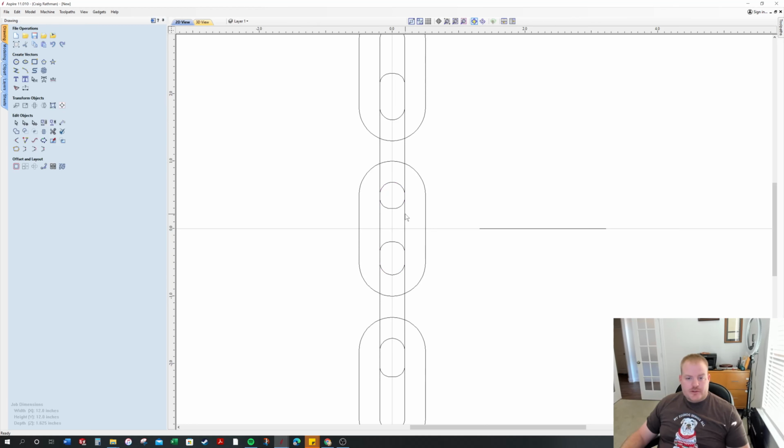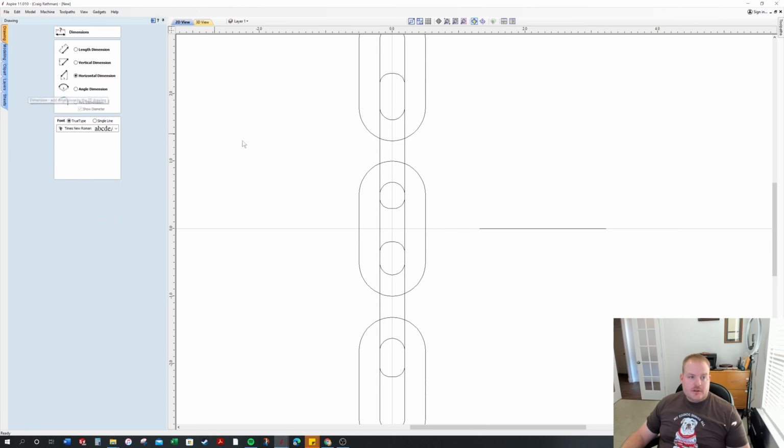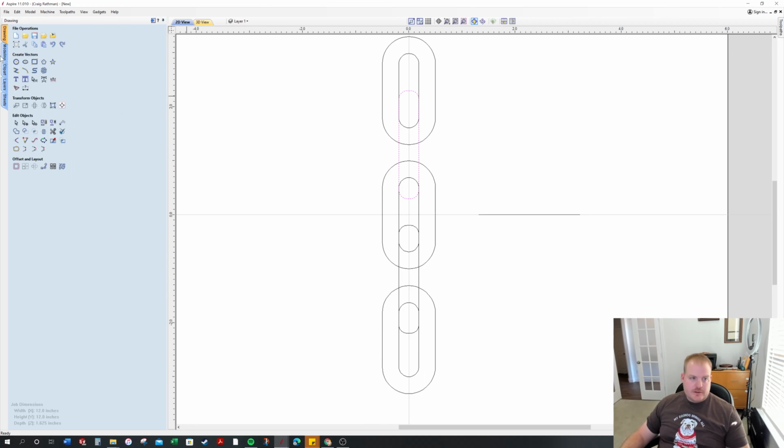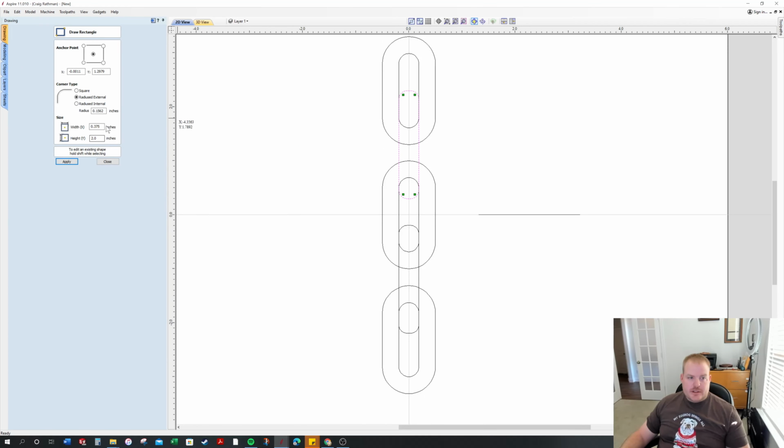And then, at least how I do it, you go over here, grab this tool for measuring, you want the horizontal, and then you want to know what this width is, and it's 0.375. And then you can leave that there or delete it. So you want to go back in there, and this is already created, so I set it at 0.375 wide, and then 2 inches on the y-axis, because that's how tall this part was, because it's the same thing, just basically rotated how it would look in real life. And then the corners or radius automatically adjusted once I did that.